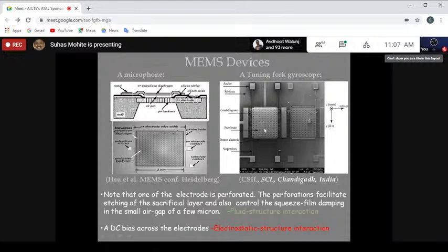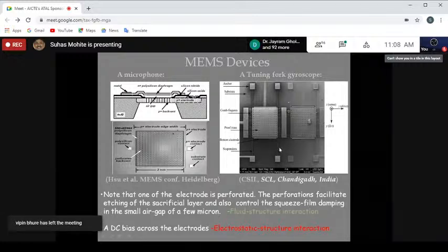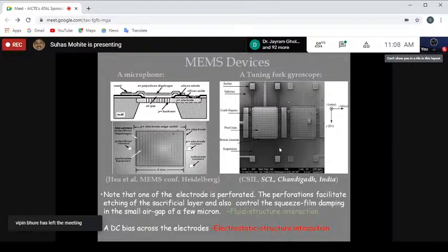But the material which is underneath the plate at its center, it will be extremely difficult for the etchant to reach there and etch out. And therefore, these small pockets are created, and the top electrode surface itself has a perforated structure like this, because these holes are etched first, and through these holes the etchant goes inside and the layer underneath is etched out. So it is the requirement of the fabrication process.